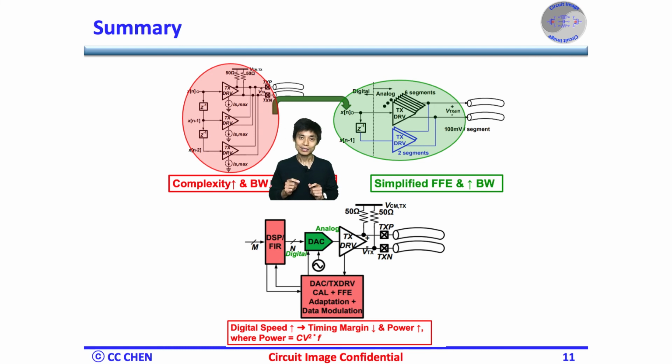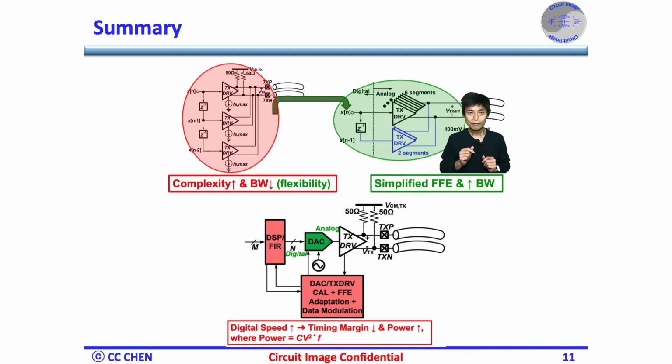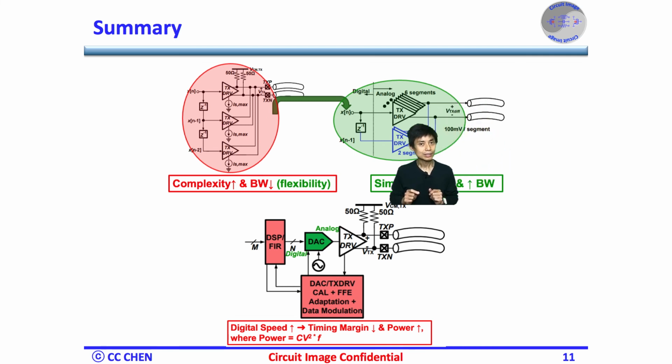In most SerDes, with up to 30 dB channel loss at the Nyquist rate, the TX FFE might only equalize 3 dB to 6 dB, and the RX CTLE and DFE would take care of the remaining 27 dB or 24 dB of loss. Therefore, a highly configurable FFE at the TX is unnecessary.